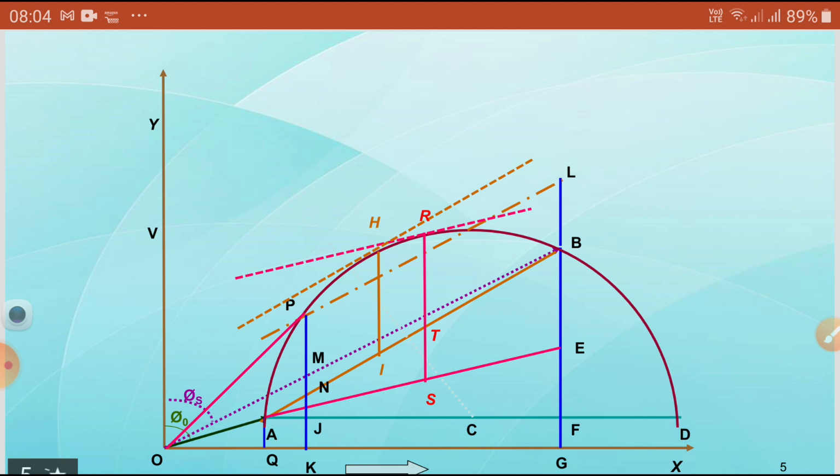That means at no load it is running at 1440 RPM. If we add some amount of load, for example 2 kgs of spring load, which you are going to apply in our laboratory, then instead of running at 1440 RPM, now it will run at 1420 RPM only. That means 20 RPM reduced due to the load.